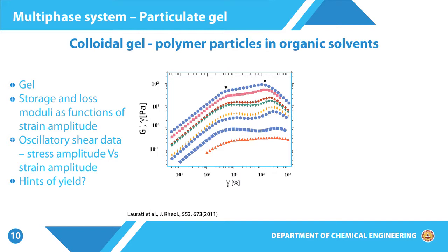But when we go to higher and higher strain, we can clearly see there are transitions, in the sense beyond a certain strain the stress increases, but it increases far more gradually, and in fact there is a decrease in stress beyond a certain strain. So, these kinds of transition points can possibly be identified as yielding phenomena which are happening in the material as the material is being subjected to higher and higher strain.